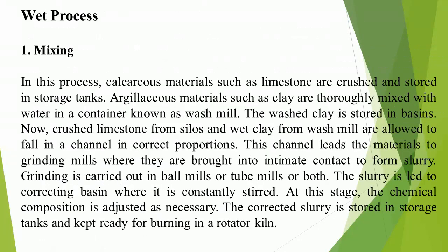Wet process. 1. Mixing. In this process, calcareous materials such as limestone are crushed and stored in storage tanks. Argillaceous materials such as clay are thoroughly mixed with water in a container known as a wash mill. The washed clay is stored in basins.